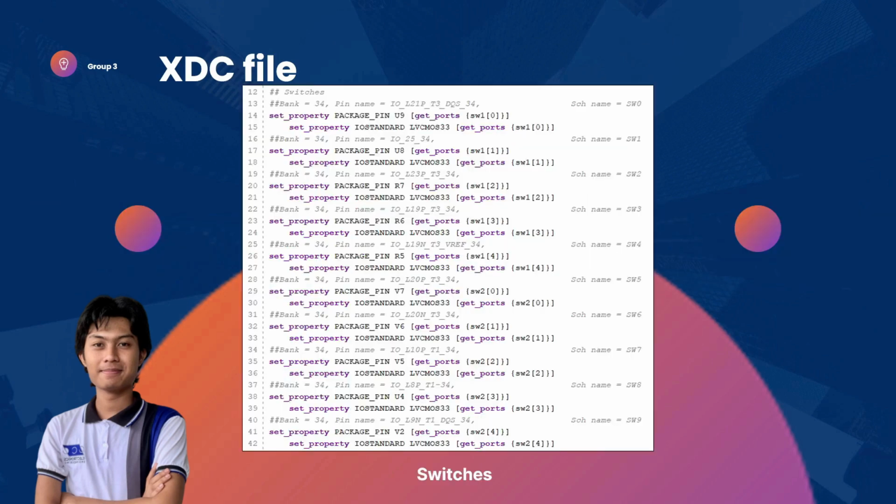Next slide. This is also part of the XDC file. Here, it shows that all 10 switches on the XDC file were uncommented and were used. Switch 0 to switch 4 is for the first 5-bit input, and switches 5 to 9 is for the second 5-bit input. All the inputs were based on the inputs used in the top module that we have discussed earlier.